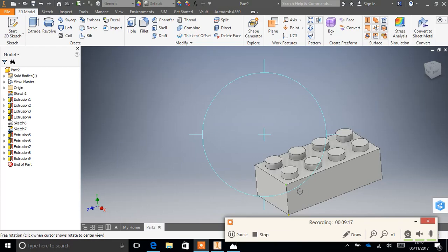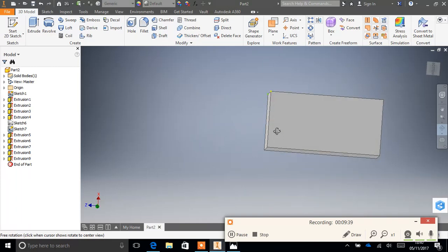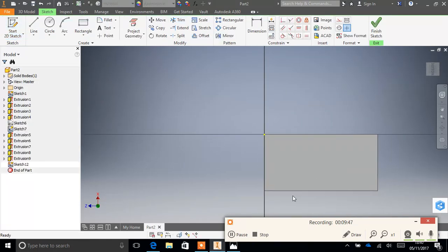So I found another image. The one that you have doesn't tell you how thick the plastic is, but it's actually 1.6 millimeters on this part here at the top. So what our brick measures currently from the top to the bottom is 9.6. So what I'm actually going to do is remove 8 millimeters, and that will be right. So I'm going to start my sketch on this side, and I'm going to work out exactly where it is and remove that material, and I'll be back with you when I've done that.